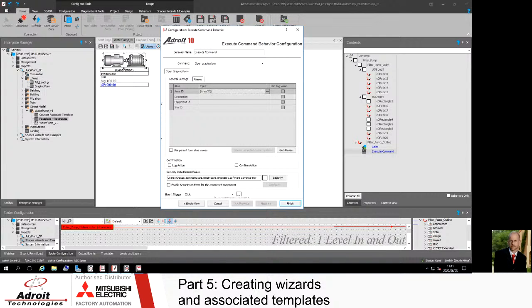Guys, it's also very important here that you use your case sensitive. If you have a different case, it will prompt you for an additional one. So if, for example, I removed that space from there, I would get two area IDs, one with a space between the area and the ID and one without. So just make sure that you follow your naming standard.